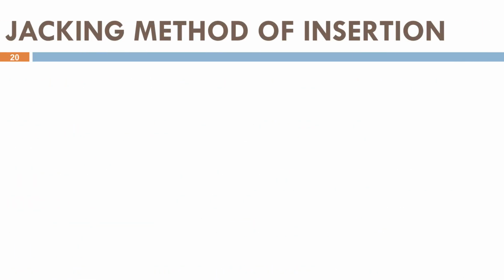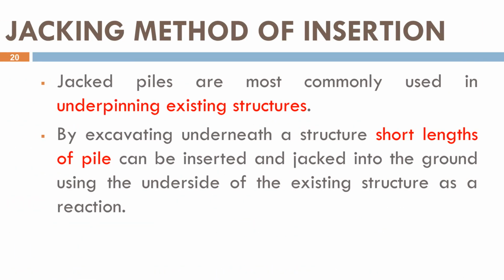The final piling technique discussed in this lecture is the jacking method of insertion. Instead of using hammer blows, hydraulic jacks apply a continuous downward force to push the pile into the ground. The reaction force is obtained from the existing structure or a specially designed reaction frame.